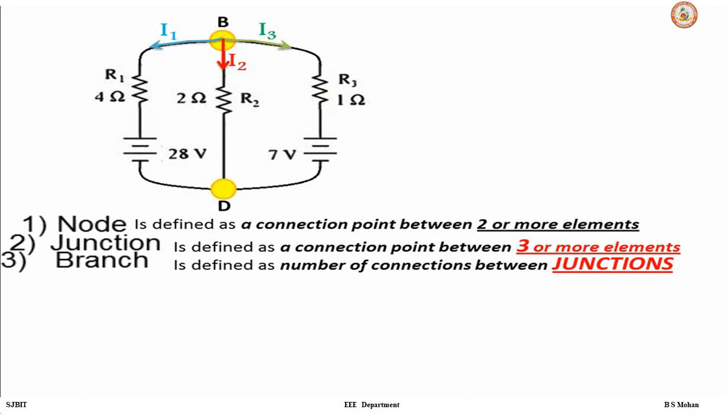We have three currents. But why have we drawn the currents downwards? Why is it flowing from B to D, not from D to B, right? So let us answer that. Here we should assume one reference point, the black one, at ground potential, and the rest, in this case only B, the other junction which is there, has the highest potential, or positive terminal.